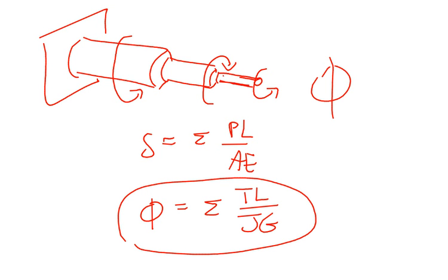And then the other type of problem that we had when it dealt with rods was the statically indeterminate problems. If you remember, that would be putting a fixed support on both ends, and then we talked about how you applied superpositioning to solve those types of problems. Same thing here.